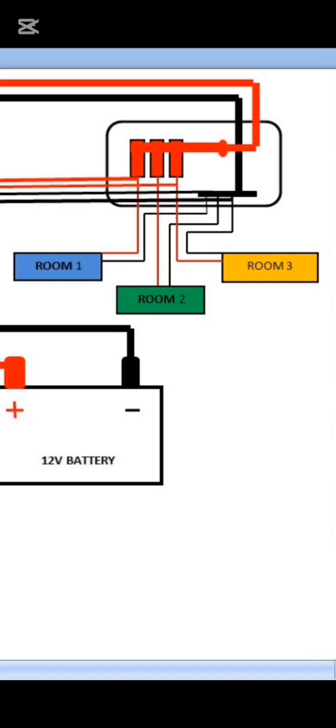So it is advisable for safety reasons that you turn off the circuit breakers of room 2 and room 3 to disconnect the power supply from the main, so that only the EPS can be supplying room 2 and room 3.